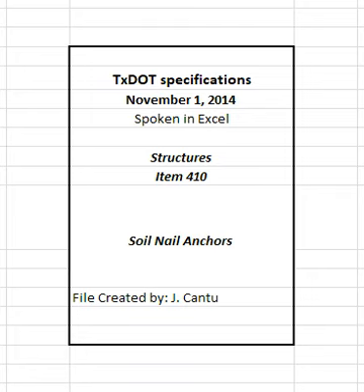Similarly, remove all pneumatically placed concrete, excess grout, or other foreign material to expose the full face of the grout column. Ensure the reaction system does not contact or interfere with the soil nail anchor reinforcing bar during the test. Conduct the following testing method. Apply test loads to soil nail anchors in increments of approximately 10% of the required test load stated on the plans. Hold each load increment long enough to obtain the gauge readings and to ensure that the readings have stabilized. Hold the final maximum test load for 10 minutes.